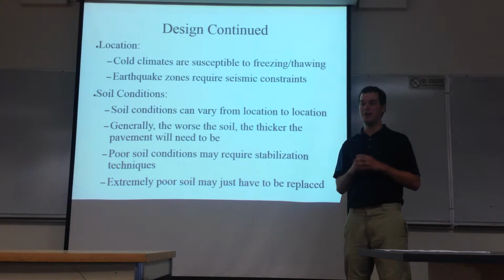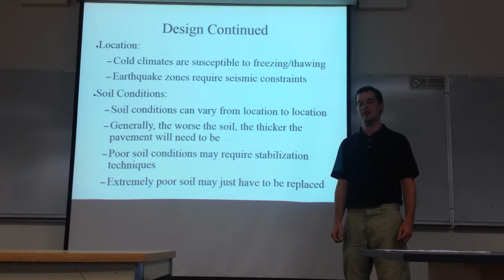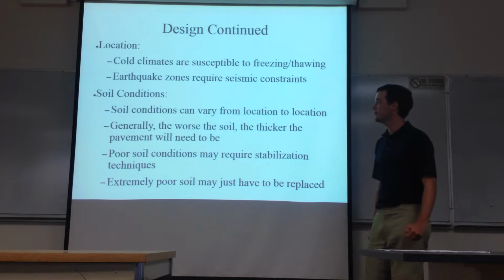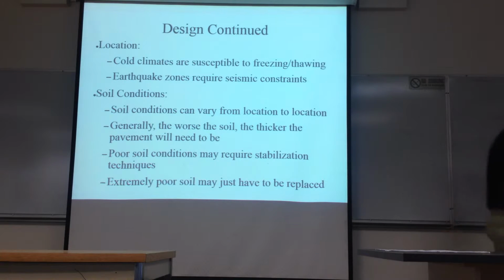When soil is very bad, to the point where it's just completely useless, we have to tear it up, sometimes up to 3 to 4 feet down, and completely replace it. And that process right there is very expensive. Let's continue with some design ideas.